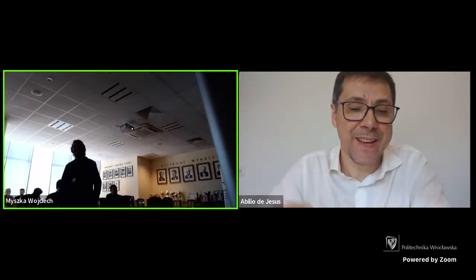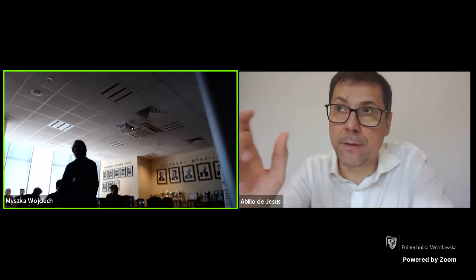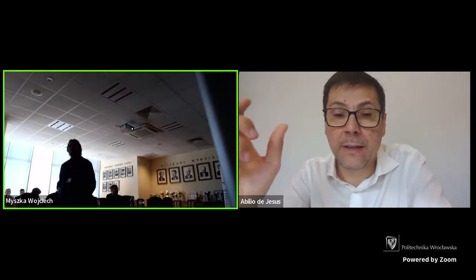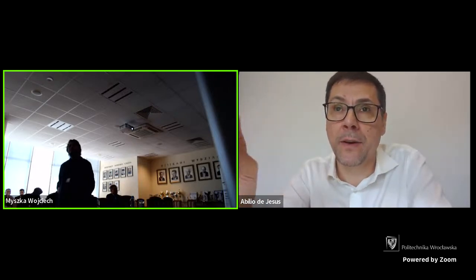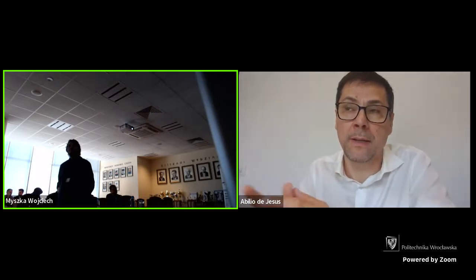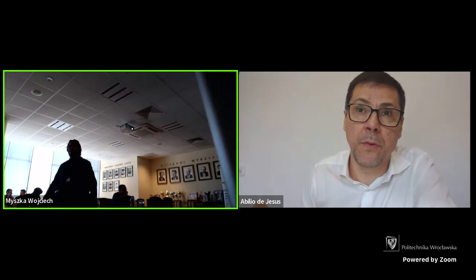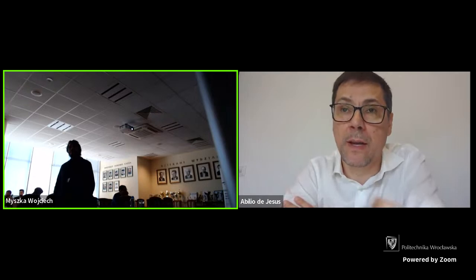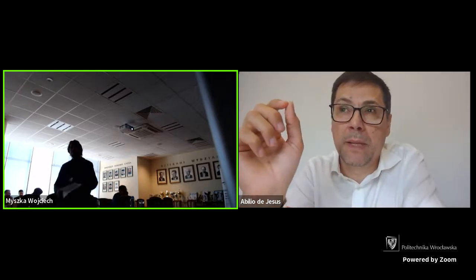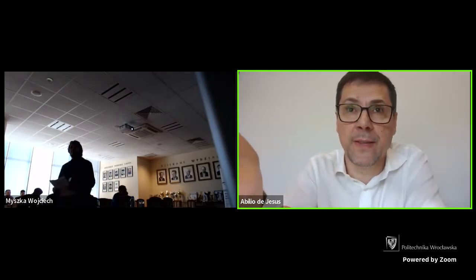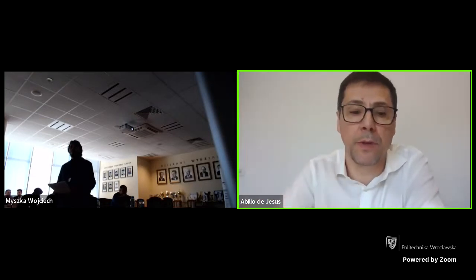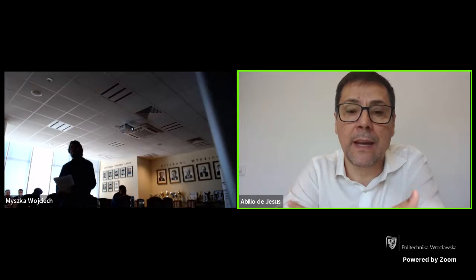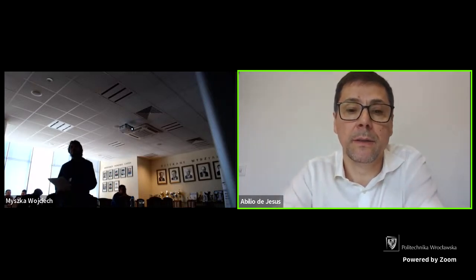Yes, sorry. So I was telling that the idea is to develop a digital twin, let's say, of the spring. And for that purpose, we rely on an elastic model, which is globally acceptable. Of course, afterwards we can run some nonlinear models or constitutive equations in some spots, but that should be done by post-processing the elastic results. Otherwise, this model could not be applicable in real time, which is our goal. Thank you.